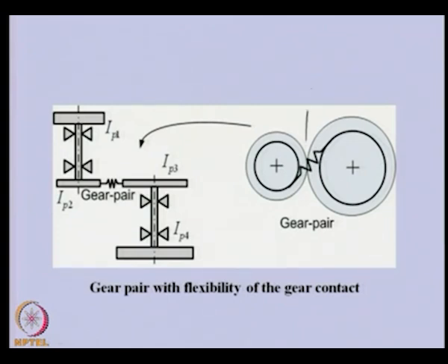So, this is basically a linear spring, that means the extension or compression of this would take place during the motion, because these two are having torsional oscillations like this, and because of this you can expect that this particular spring will get extension or compression depending upon the relative angular displacements of these, and that will depend not only upon their relative twist, but also the pitch diameter of the gears.